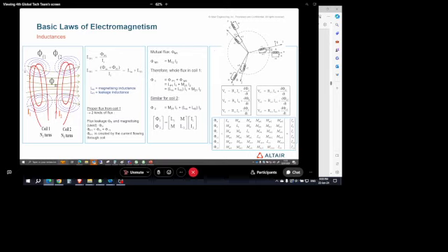So why am I talking about main magnetic flux? Because there is a second coil in front of it. So I am going to induce magnetic flux variation. It's the same thing if I produce magnetic flux on the stator, and this magnetic flux will move from the stator through the air gap to the rotor.